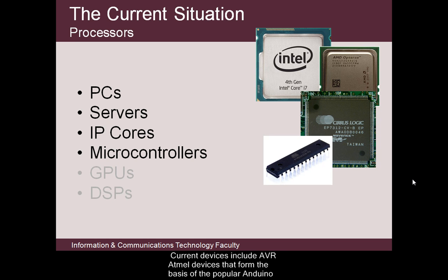Microcontrollers are complete self-contained computers on a chip, designed for embedded instrumentation and control applications containing memory and I/O functions such as pulse width modulation for driving motors. The emphasis is on low cost and low power consumption. Current devices include the AVRs that form the basis of the popular Arduino range of single-board computers.